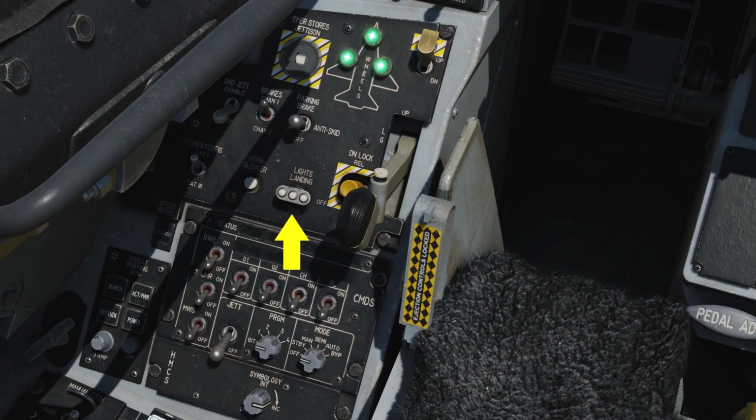The landing and taxi light switch allows you to set this light for landing and taxi operations. The downlock override button allows you to raise the landing gear with weight on wheels. Maintenance would be a prime example. Related, the ground jettison switch will allow you to release freefall bombs with weight on wheels. The brake switch can be set to anti-skid or parking brake modes. You can also turn it off, of course, too.